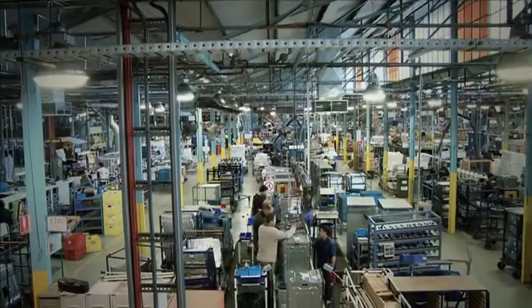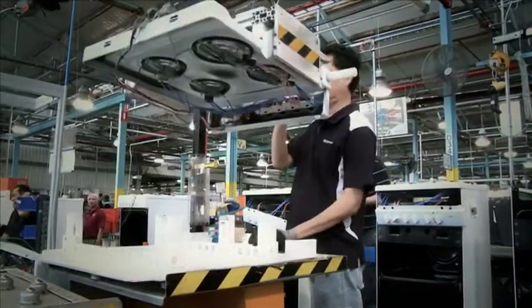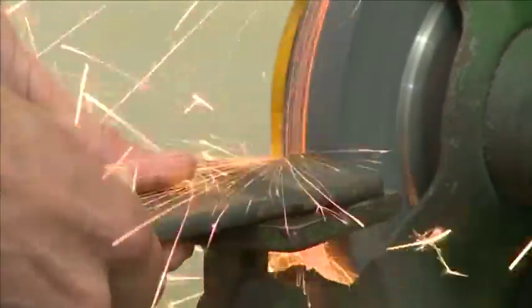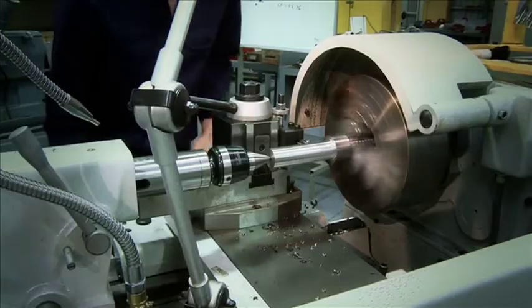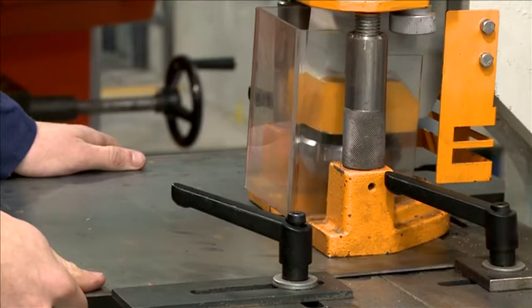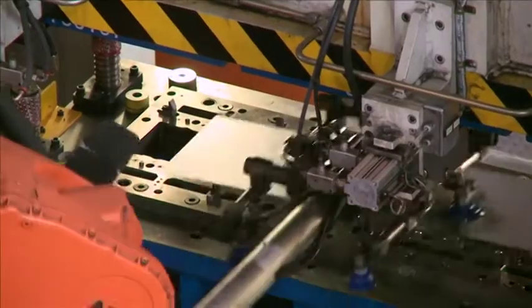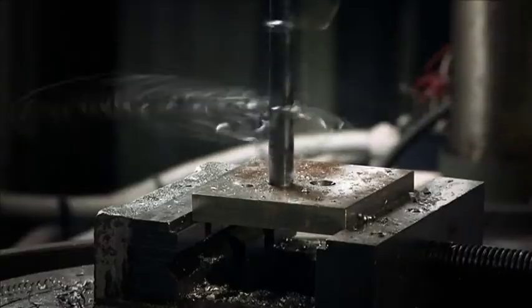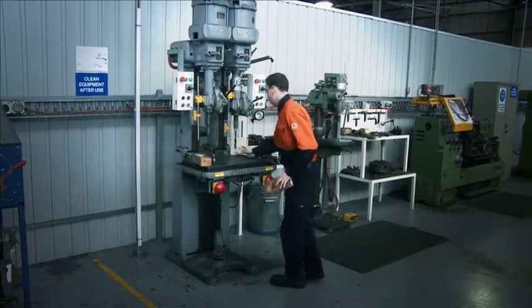In the engineering environment, most plant, machinery and processes involve moving parts. Production lines, forklifts, lathes, milling machines, grinders and cutting equipment all present hazards. Common machinery hazards include entanglement, caused by loose clothing, long hair, gloves or jewellery; cutting or puncturing, caused by tools or moving machinery; crushing, caused by opening or closing of nip points or pressing actions of machinery; flying particles such as swarf. There is a series of steps that you need to follow to ensure your safety.